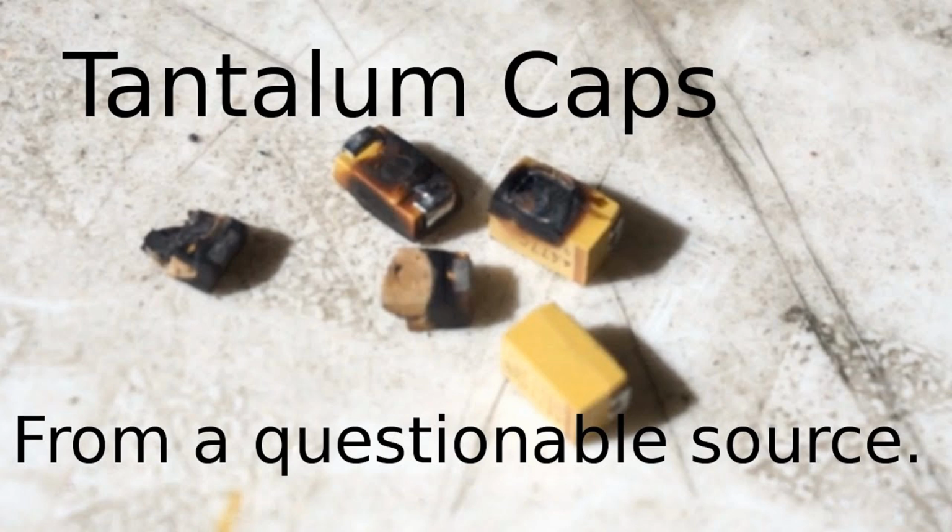Low ESR. Quickly responds to changes in current demand and reduces energy loss. AC filtering. Blocks low-frequency noise and allows desired signals to pass. Timing applications. Used in RC circuits to control time intervals. The primary role of a tantalum capacitor in an electronic circuit is to provide reliable energy storage and release, smooth out voltage variations, filter signals, and maintain stability in the presence of electrical noise or spikes.